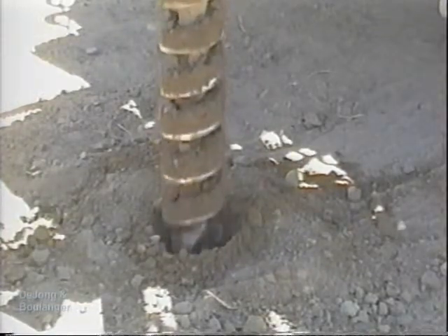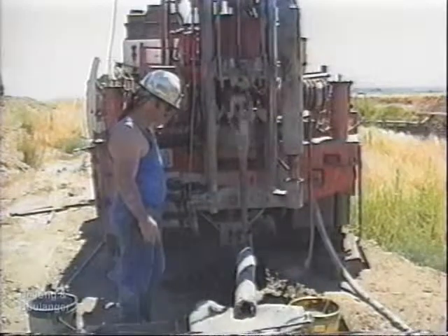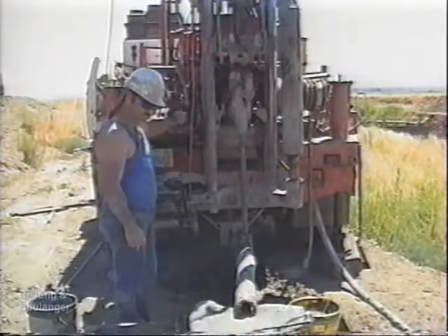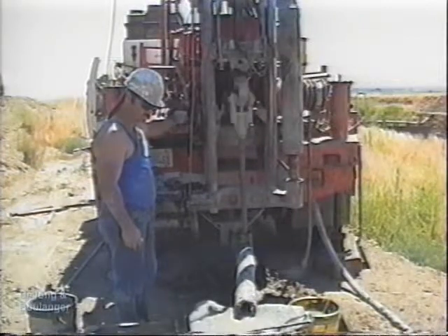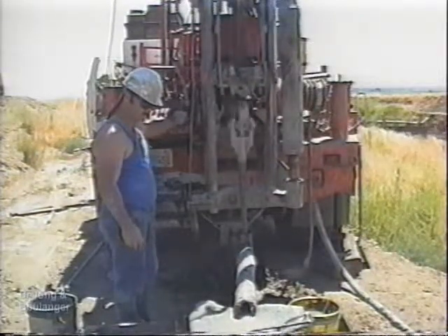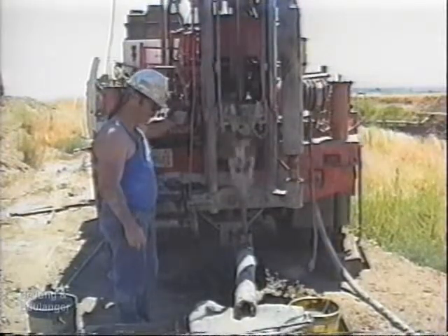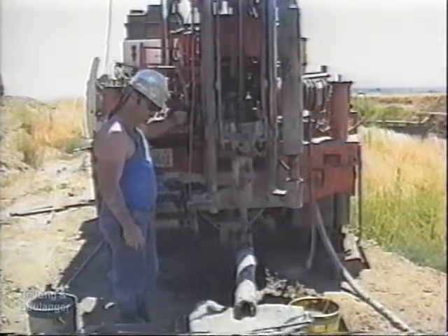It is recommended that the diameter of the borehole be 4 to 5 inches. As the diameter of a borehole is decreased, the penetration resistance is likely to increase. Side discharge bits should be used when rotary drilling because the jetting action of a face discharge bit disturbs the soil at the bottom of the borehole. Most drill bits can be modified to be side discharging by spot welding on baffles to deflect the drilling mud sideways.